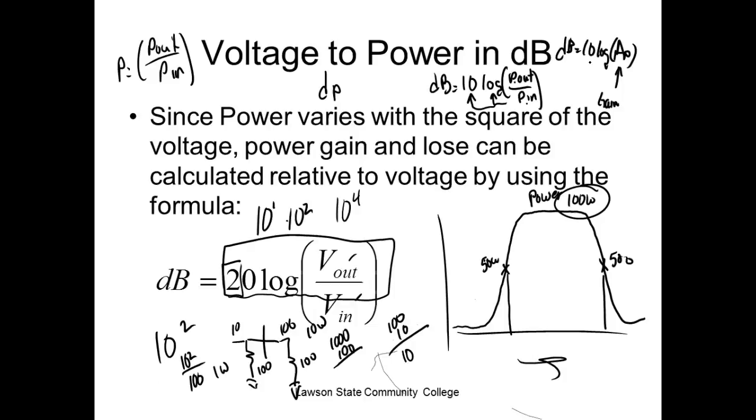So you put that little thing in there, right? And that's all it was, just a little what? Impedance matching transformer. And you went from like the twinplex or the 300 ohm over to the coax. The flat, yeah.